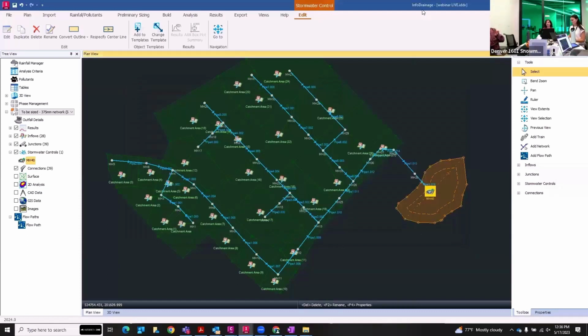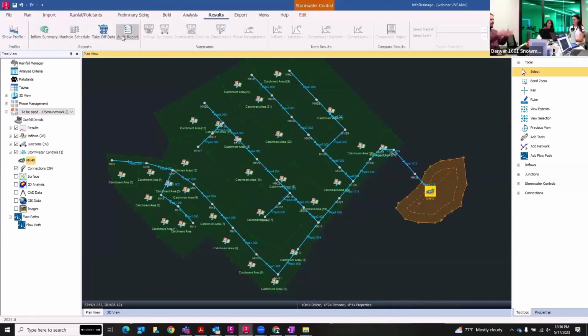Something we won't touch on today, but another feature that I think is pretty cool and goes in line with that: when you're validating, it's checking whether this is an engineering-sound design. Do we have pipes that are running out of the ground? Are we forgetting rainfall? Then there's also the audit reporting, where you can plug in specific standards for velocity, depth, all of that, diving into design and analysis a little more. There are a lot of really cool checks and balances in there, so I always like to touch on that one. It's awesome. All right, so let's send this back to Civil 3D.